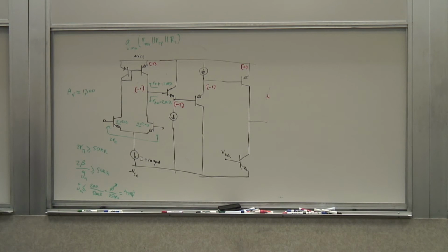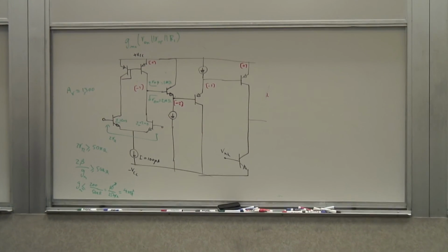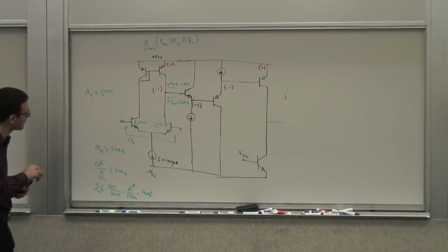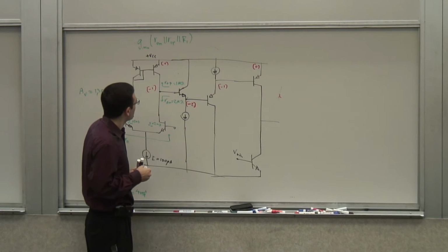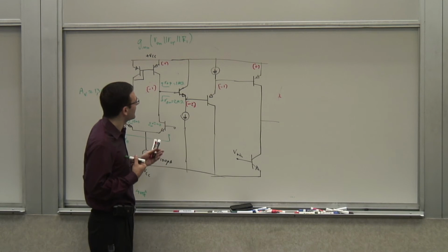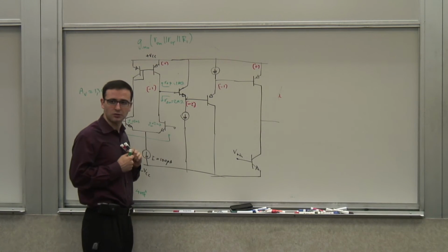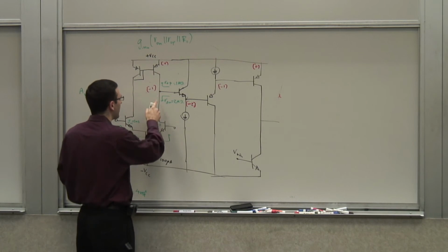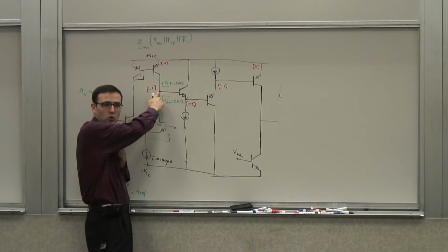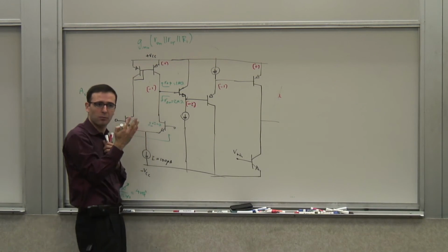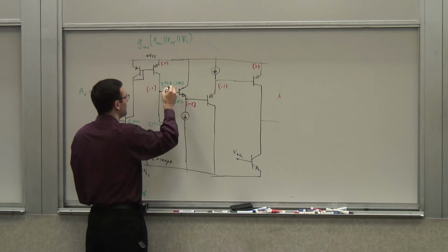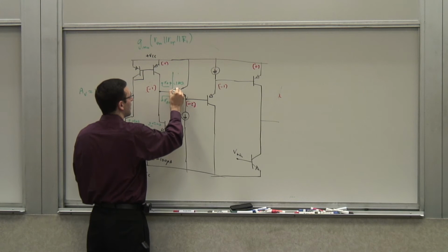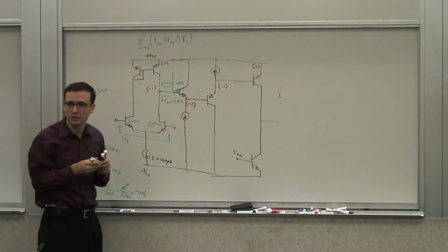So now the other thing I need to do, really, well, not worry about that for a second. Sorry. Okay, so to calculate my gain of the first stage, what do I need to know? I need to know the impedance on this node, from this node to AC ground, really. I know 2 parts of it. It has 3 parts. I know this part and that part. But there's another part, the input impedance looking here, that I don't know yet.